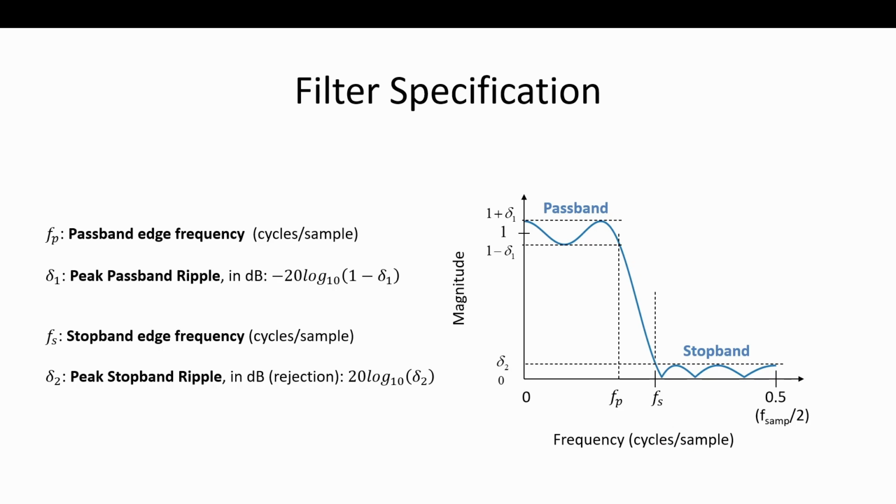So whatever your frequency axis was, if it's in hertz, which is cycles per second, and our units of time are seconds, if we change our units of time to be samples, then it becomes cycles per sample. You divide by the sampling rate and it becomes cycles per sample. So the sampling rate itself divided by the sampling rate is 1, that would be 1 cycle per sample. It sounds a little confusing, but it's just another way of representing the frequency. Then everything will scale. When we scale the filter, it's very convenient. So you'll see that throughout this presentation.